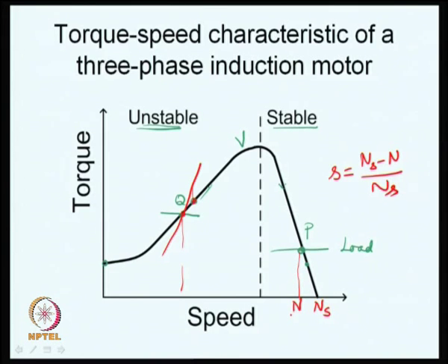So, the rotor side resistance in a motor, you would have seen in an equivalent circuit, is R by S. Now, in this case the slip is very small and therefore, R by S is substantially high. If you take the next case, this operating point Q, the slip corresponding to it, let me call this as n subscript Q, just to distinguish it from this n. So, nQ minus ns is now very high and therefore, the slip is very high. If the slip is very high, R by S is actually very low.